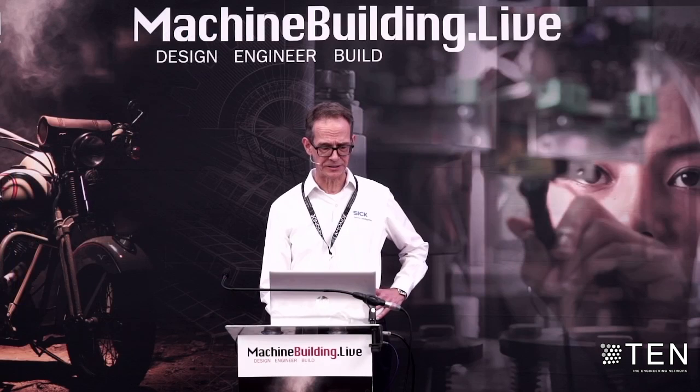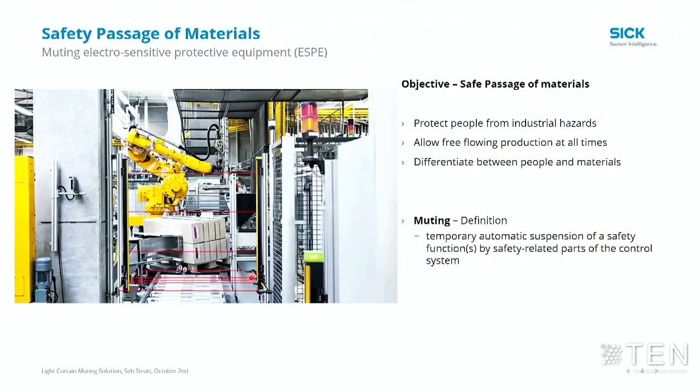And those of you with good eyesight can probably see at the bottom of the light curtain there's an array of 4 sensors, and these are there to pick up the pallet moving into and out of this palletizer cell, and thereby instigate a mute of the light curtain. So the purpose of the solution is to protect people from industrial hazards, number one, allow free-flowing production at all times, that's critical to success, but must be able to differentiate between people and materials, and this is where muting becomes an awfully complicated exercise.